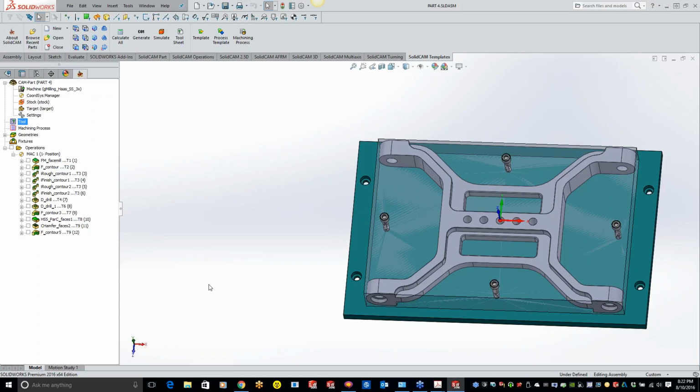You can put that wherever you like, but since we already know where the center of the rotary table is, by mounting it on there, we know it's exactly 8 inches up. That's why it's the most common place, because everybody has that work offset written down and goes from there.